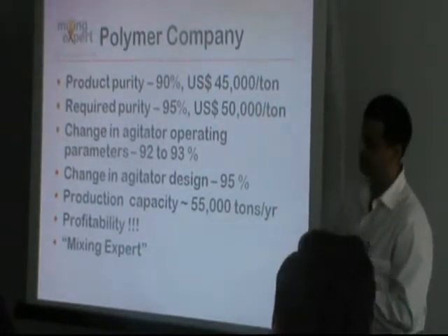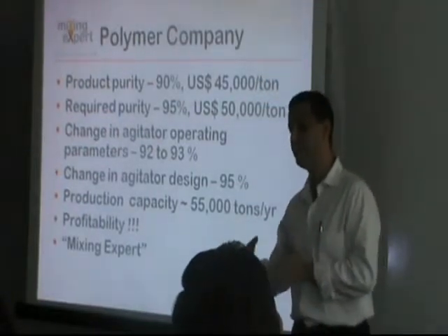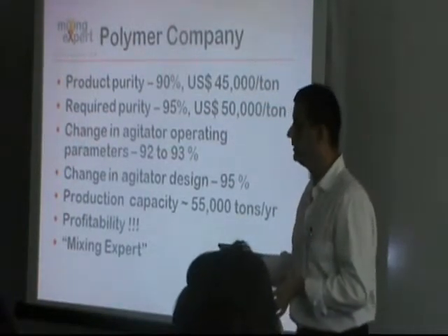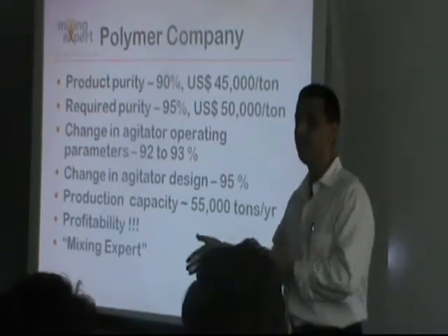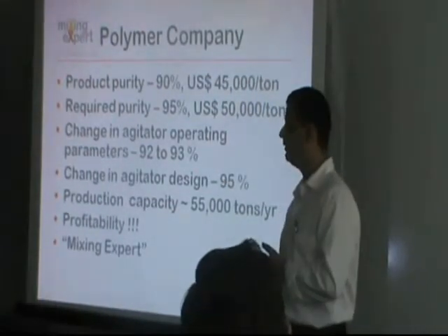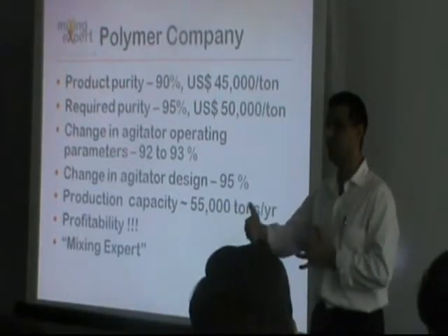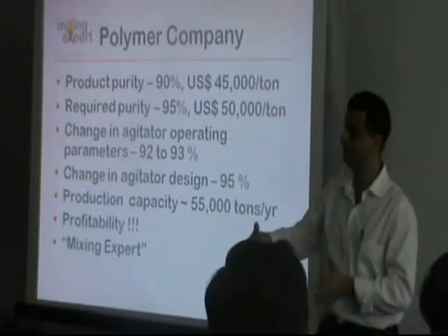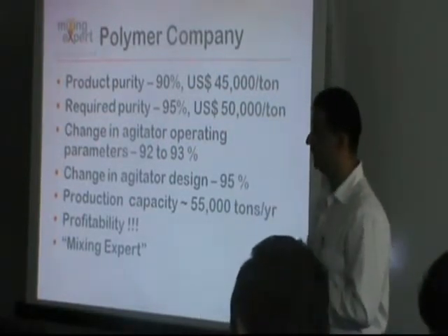That was an operating plant, there were no possible changes thereafter. With the impeller diameter increasing, the power consumption again increased. So we had to check the mechanical capability of the equipment, and we upsized the motor to the extent where it was possible to run the system without making any mechanical changes or any major changes.